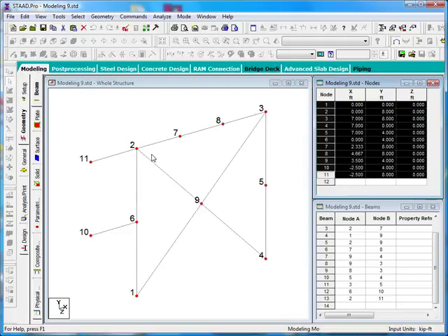As a final comment to the copy and paste beams function, I'll just note that where we used this function on a single beam at a time, it is possible to use the copy and paste beams command on more than one member at a time by selecting a group of members and executing the same command sequence.